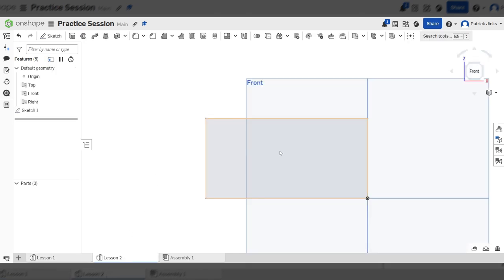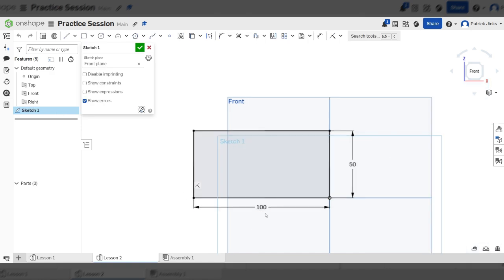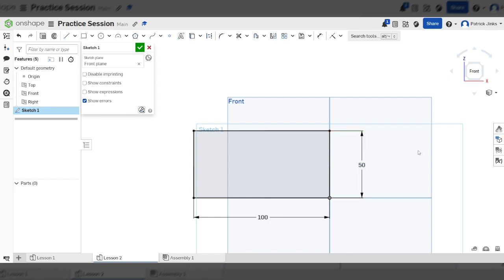All I need to do to go back into the edit phase is find the sketch, so it's sketch 1, and I double click it, and it comes back. Now, I've lost my opportunity to just type numbers in and edit. Once you've drawn the rectangle, you've got one opportunity to just type a number, press enter for the height, and type a number, press enter, to set the width or the length. That doesn't mean it's fixed like that, not by a long way.